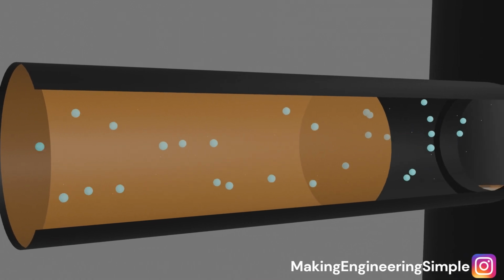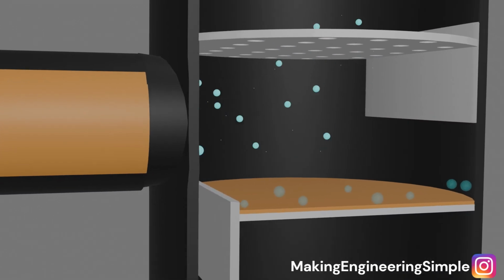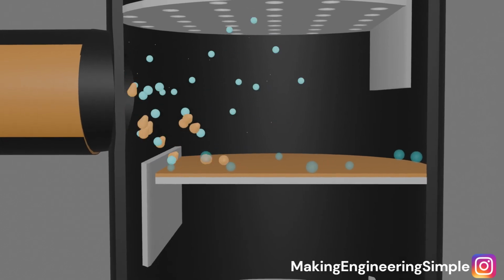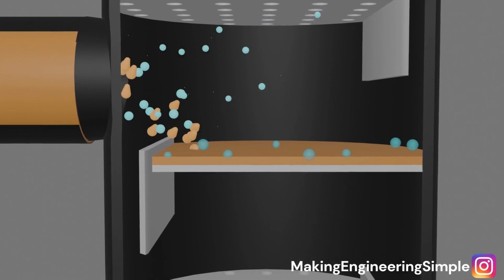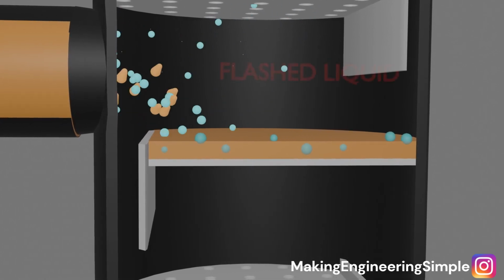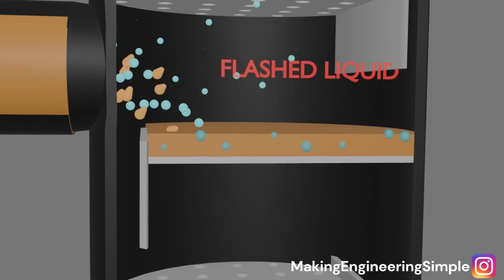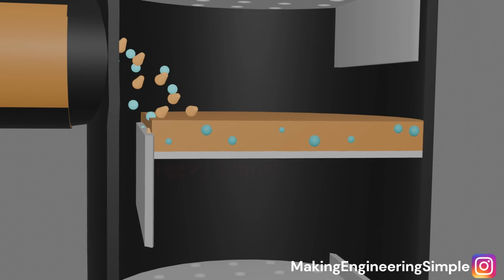It absorbs thermal energy, bringing it right to the edge of its boiling point as it approaches the distillation column. As the heated feed enters the column, the sudden drop in pressure causes a portion of the liquid to instantly vaporize. This is called flashing. The lighter vapors immediately rise upwards, while the remaining heavy liquid drops down to flow across the plates.